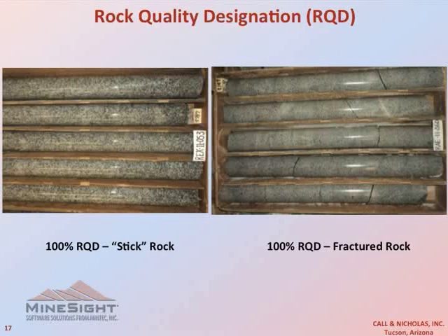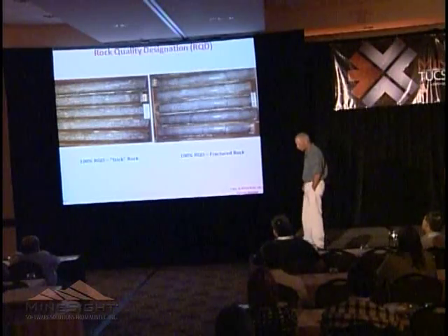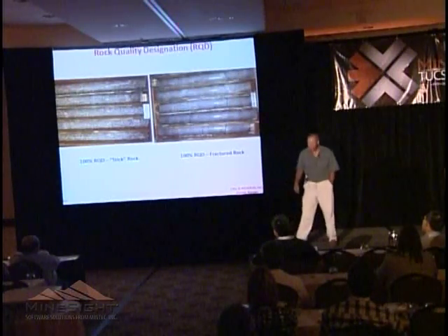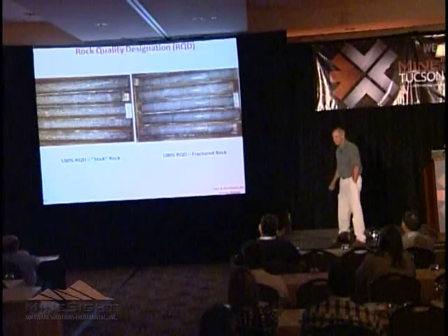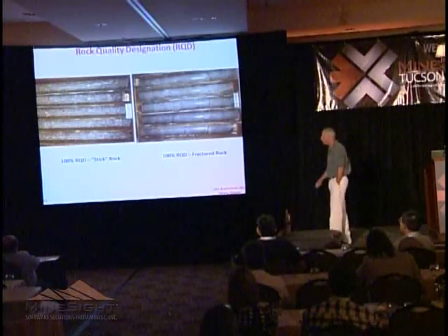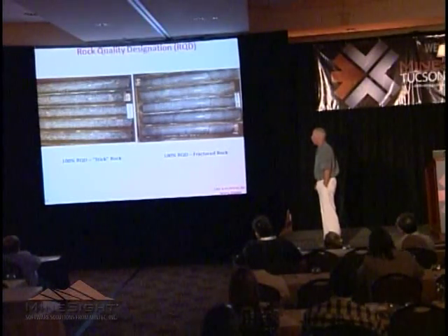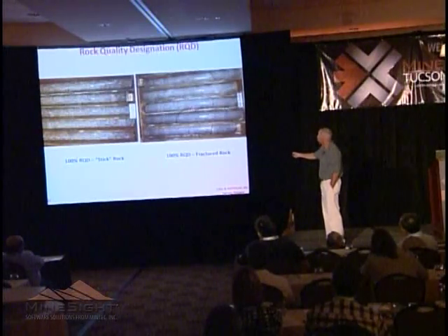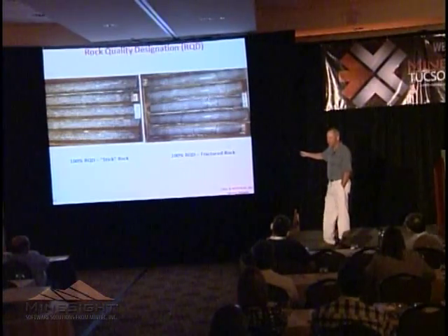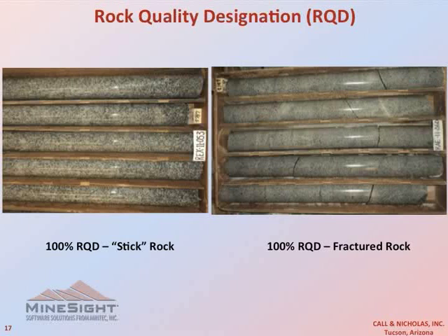So a lot of times, this is what we find, is that RQD doesn't really tell you the whole story. With these both being 100% RQD rock, you need to know where these joints are and what the spacing is. So a lot of times, RQD alone doesn't tell exactly how the rock is going to behave.